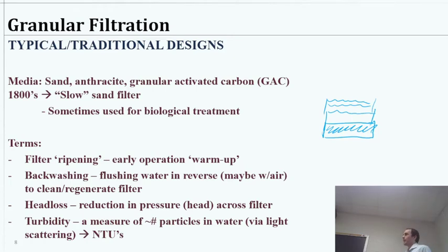And lastly, it turns out that it's actually good for the filter to have a little bit of stuff stuck to it to begin with, and then it becomes much more sticky to everything else. And maybe the sand grains have to kind of settle in and compact just a bit and get into place. And so typically about 15 minutes of operation is good for that ripening stage, takes care of all those things. I guess if it was a brand new filter, maybe you'd need more, but this ripening then is something like 15 minutes of normal flow through it so that we can avoid those issues.